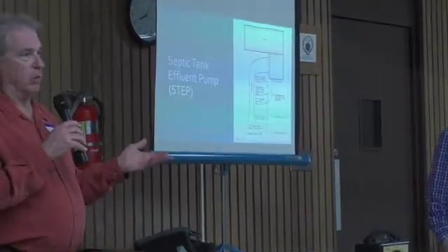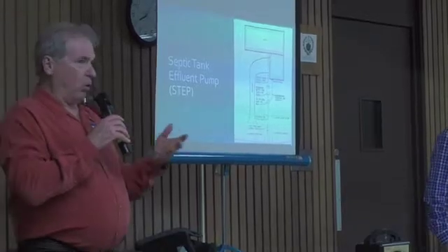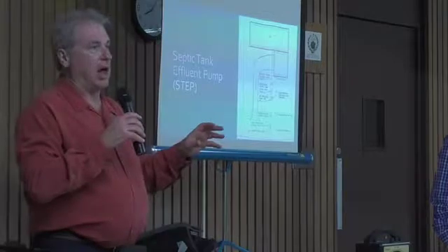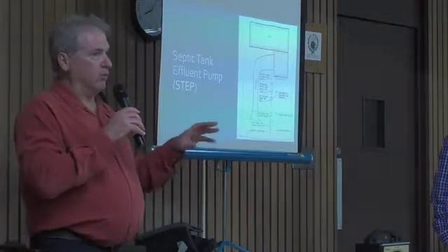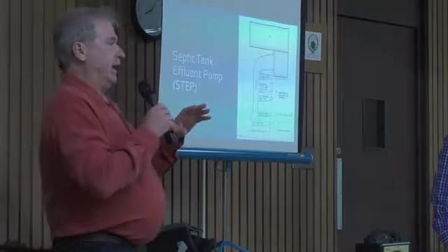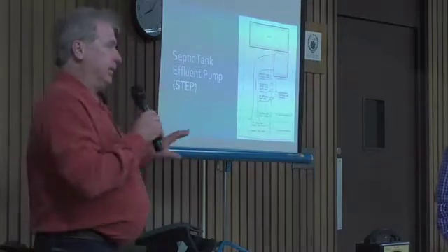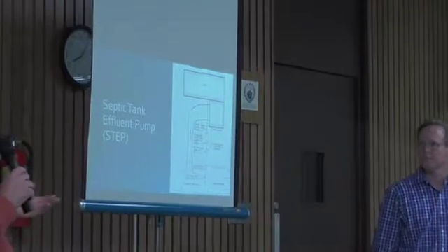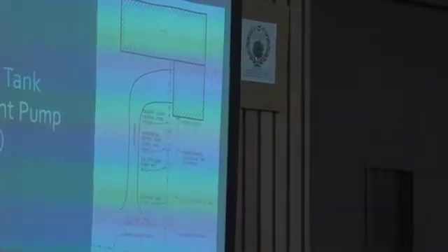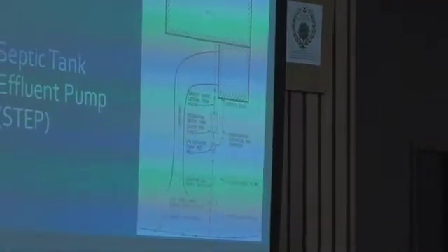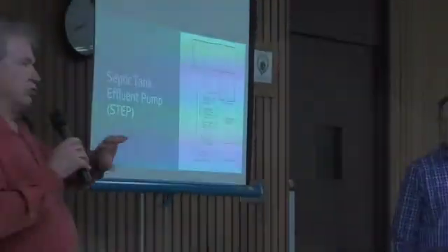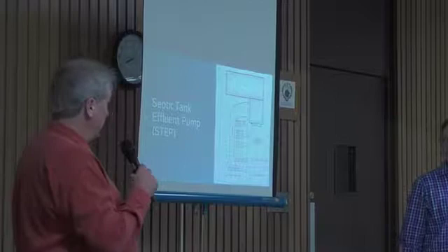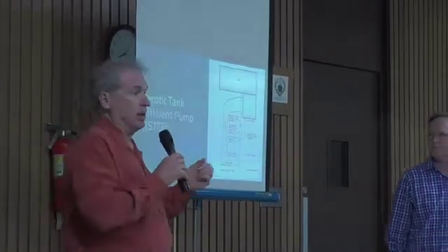That's a pretty traditional way where you have 4-inch laterals serving each house, and they go out to 8-inch lines that go from manhole to manhole, and the lines get deeper and deeper as they flow downhill, and ultimately you reach a point where you don't want to dig any deeper, so you put in a pump station and you lift the sewage up and transport it to another area where you either have it flow again by gravity somewhere, or in this case, go to a treatment plant.